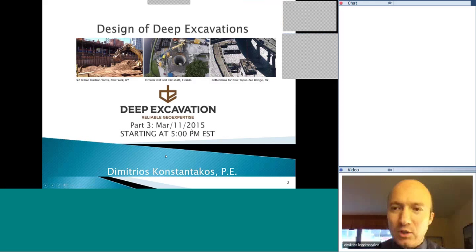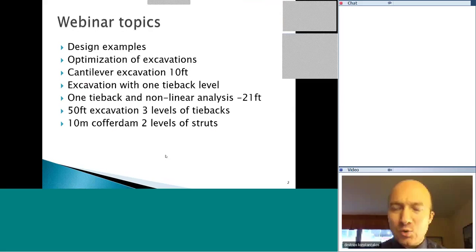On this webinar, which is part 3, we will be covering different aspects. We had two webinars in the past weeks on the design of deep excavations, looking at specific examples. So we're going to be looking at how we can optimize excavations. We're going to be looking at the cantilever excavation, 10 feet, roughly 3.5 meters. How to optimize an excavation with 1 tieback level. Look into a nonlinear analysis with 1 tieback level. We're also going to look at that excavation that we did 50 foot deep, roughly 15 meters, with the 3 levels of tiebacks on the previous webinars.